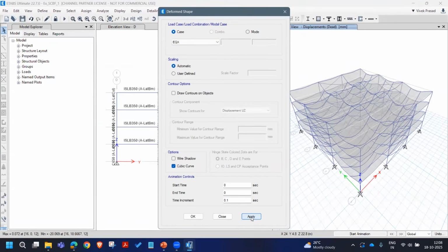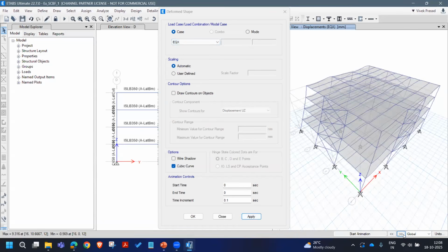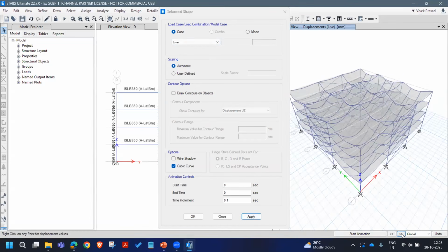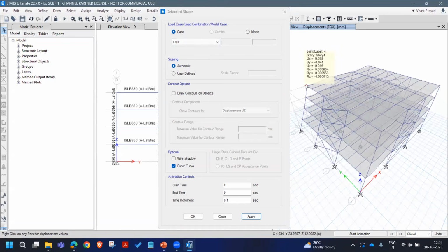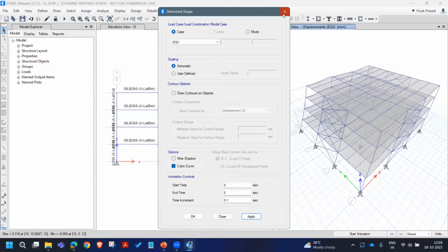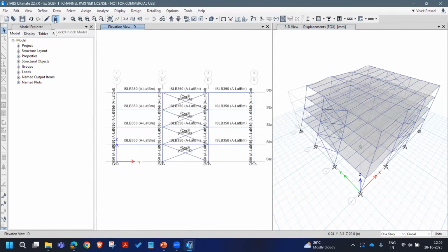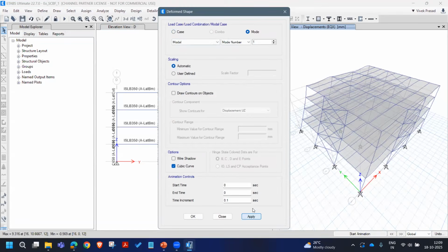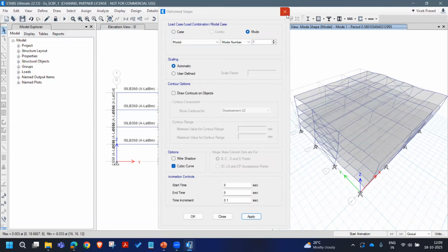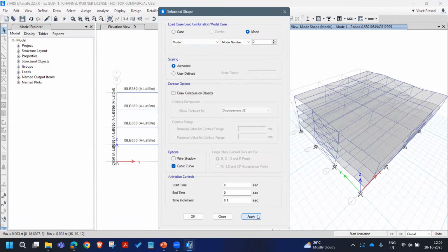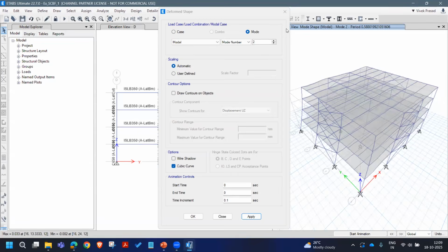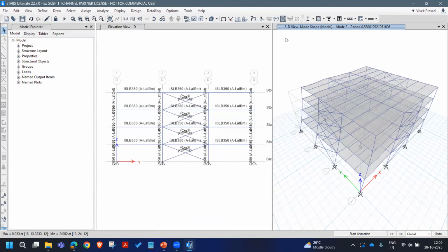The deformation for the gravity looks fine. This is for lateral, X and Y, everything looks fine, right? Deformation is about 10 mm at the top level. Now we have used the default settings when you start with the program, especially for the end length offsets. Let us also see the time period. It is 0.58. Building is symmetric. It's expected.